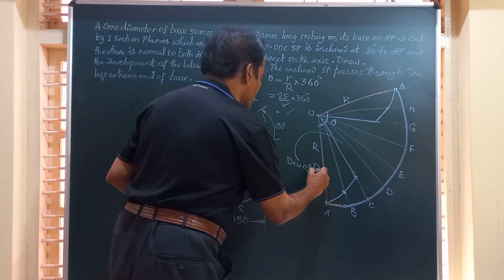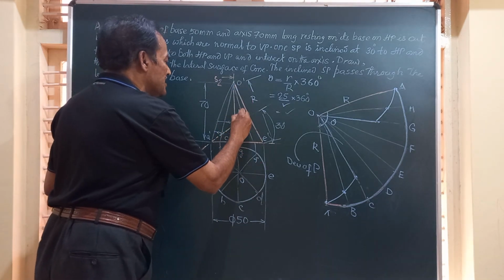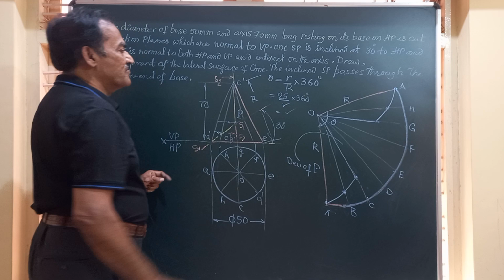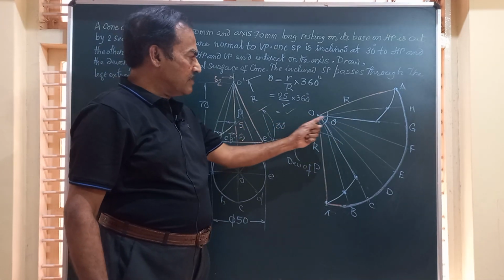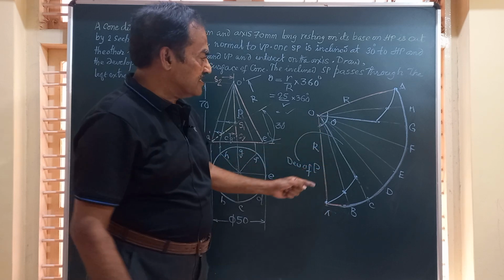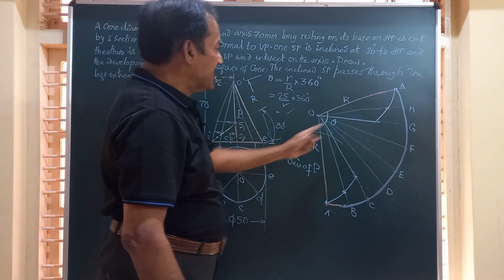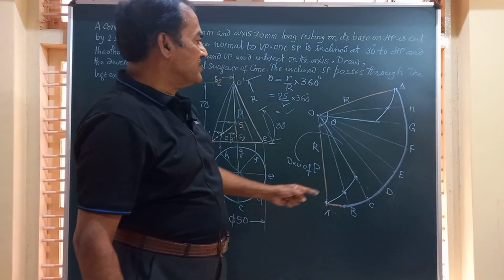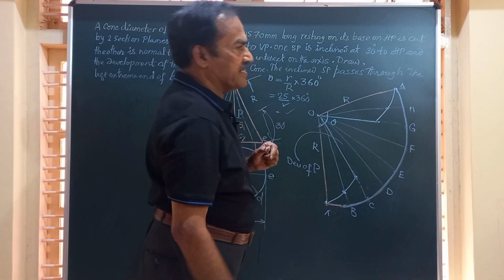That is the development of P. P is this part which is shown in color here. I will mark it as P. Friends, you can see even though it is a cone, you have some part with straight lines. That is, this part is a straight line, whereas the bottom is completely retained. I have shown it by a visible line. Vertex is included, so I have drawn it completely.